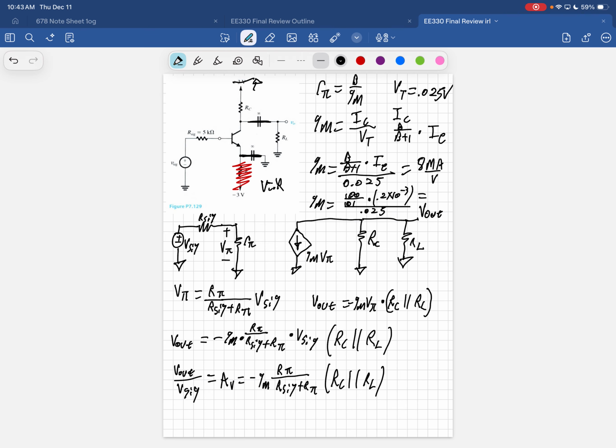Yeah, so coming back to this, we have GM now. Did we solve for RPi? Oh, RPi is just based off of GM and beta. Yeah. So we have RPi. We have our C already from the previous section. We have our L from the previous section. And our sig is given. Our pi we derived. So you plug all of that stuff in here, and you get